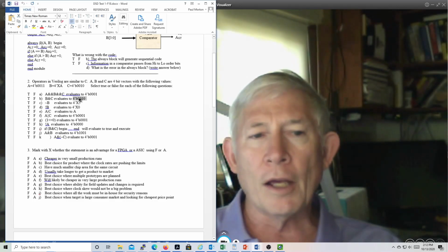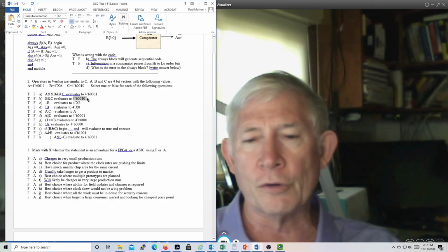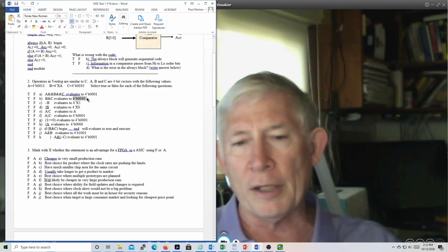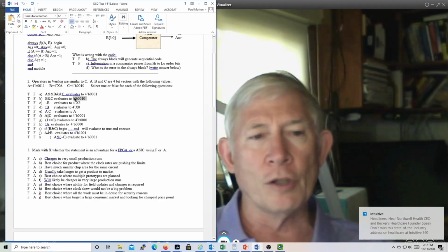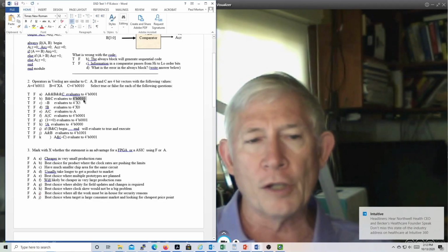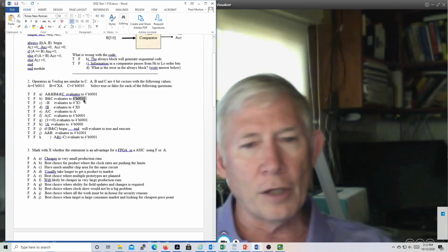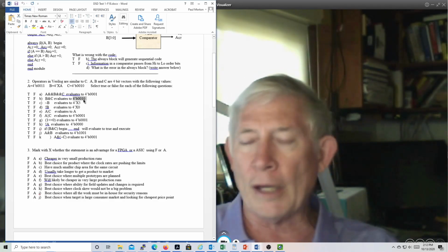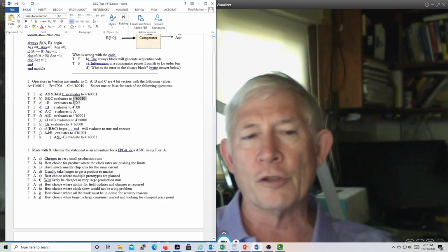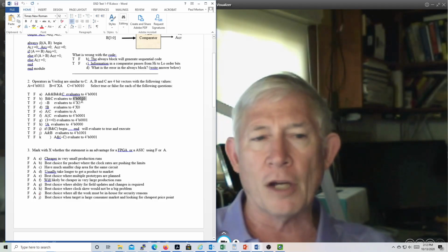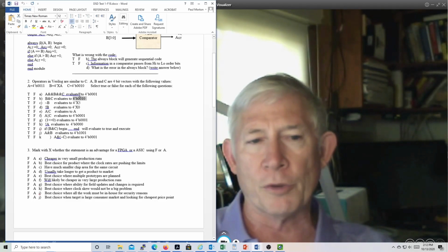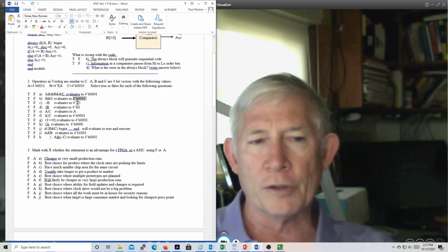You should try and make the number of digits you type in correspond to the number of bits. So if you do 8'h, you should have 2 hex digits. If you have more or less, and then there's also issues if you make it signed, it can get really crazy. So try and make sure you match up the number of bits with the number of bits you actually define, whether it's in hex or decimal or binary.